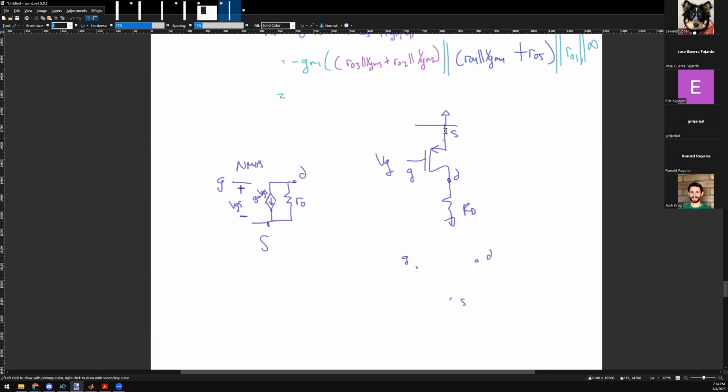Just think component by component. The MOSFET model is exactly the same. The arrow points from drain to source, and VGS goes from VG to S. This is now a PMOS device, but because we didn't flip it, you have to be careful when you connect it. The source connects to ground, the drain connects through RD to ground, and the VG goes to VN or some VG.